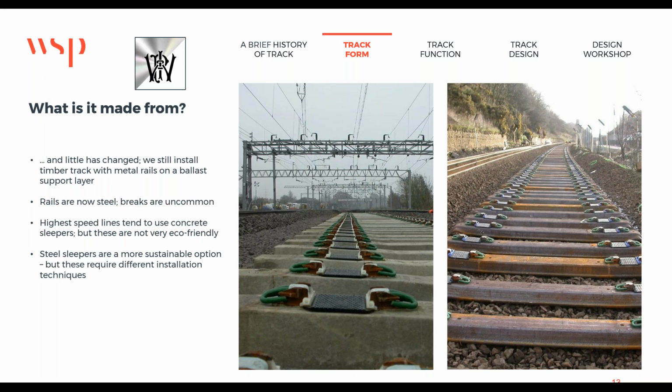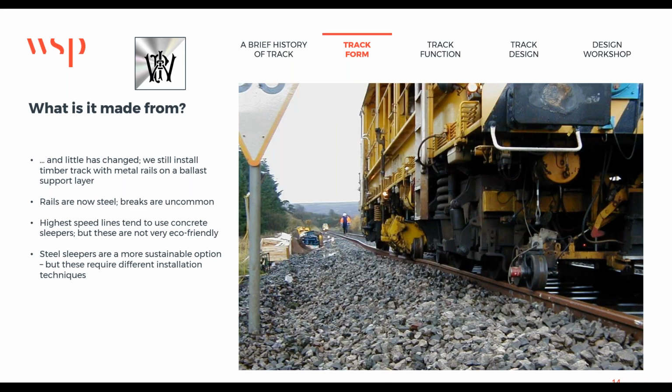In the UK, Network Rail engages in a programme of track renewal in each region, which generally involves a like-for-like replacement, with worn-out tracks being replaced by modern track forms. You use crushed rock ballast for track support, and that's still preferred due to its low cost. It's got excellent drainage properties, and that's vital, for the cyclic loading and unloading wears the ballast grains down. That creates fines, which then block the drainage pathways, and dirty ballast needs to be cleaned or replaced. So ballasted track forms are still the norm.